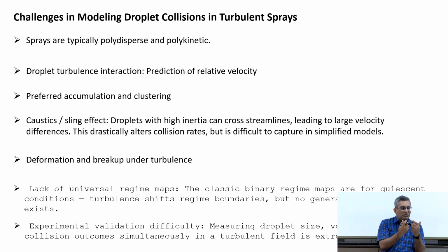So basically the bottom line is that you have an average flow field, and you have an instantaneous droplet velocity. Now, it does not make sense, because what you need is the relative velocity between the droplet and the gas flow at the same time instant, because we cannot study this in a statistical sense. It is an instantaneous phenomenon, an unsteady phenomenon with a very short time scale. So obviously your simulations will have some shortcomings. On the other hand, if you do DNS with particle tracking, it is computationally expensive.